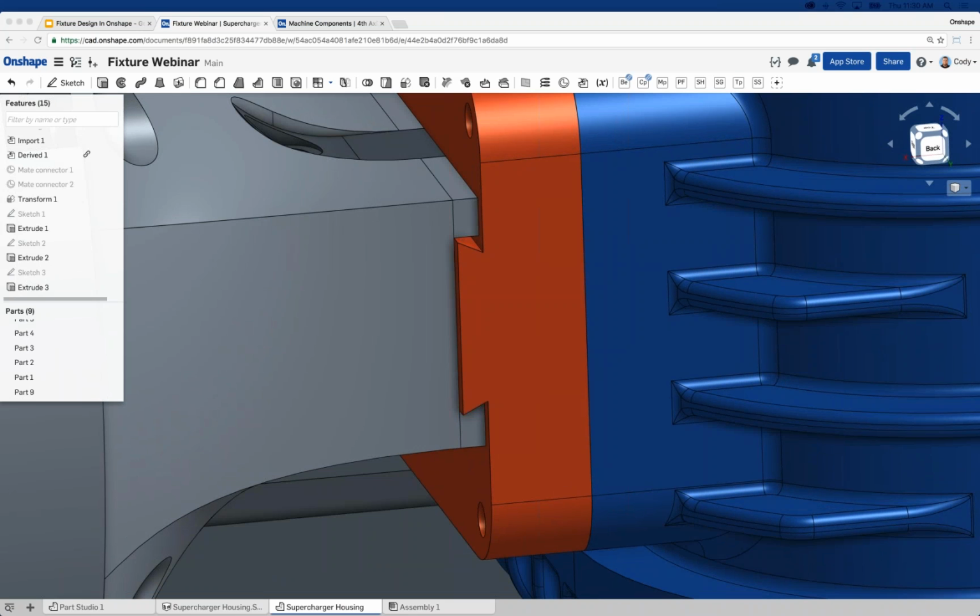Next question, I think very similar to the last one. What if I wanted an offset between the two dovetails? I would use offset and not the convert or use command. So a moment ago, I just clicked the edges and hit use. Here you would click the edges and hit offset, and then define however much offset you want between them.